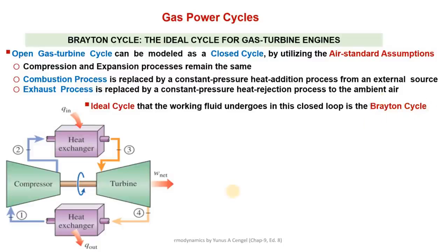So in case of steam turbines, if you remember, those turbines rotate in the currents which are caused by the hot water vapor. So it was actually hot water vapors which were doing work in this turbine, and they form a part of a closed water cycle in which water condenses here and is then heated until it evaporates here. So steam turbines therefore do not come into contact with the fuel, right, which is burnt outside in this heat exchanger.